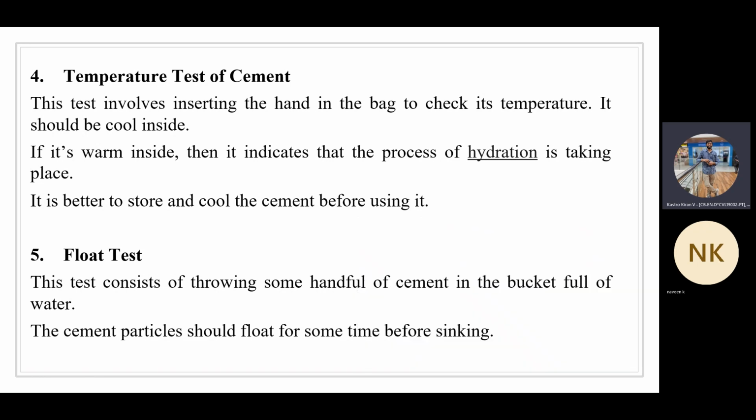Again, if you ask me what is that some amount of time, is there any indication that it should stay for 2 minutes, 3 minutes, something like that? There is no clear cut indication for that, but you should be visually able to see whether the cement is floating at least for 15 to 20 seconds on the surface of the water. After 15 to 20 seconds or 25 seconds, it can sink. Immediately it should not sink. That's called the float test. This is also one of the tests that you can perform in the site condition or in the field condition.